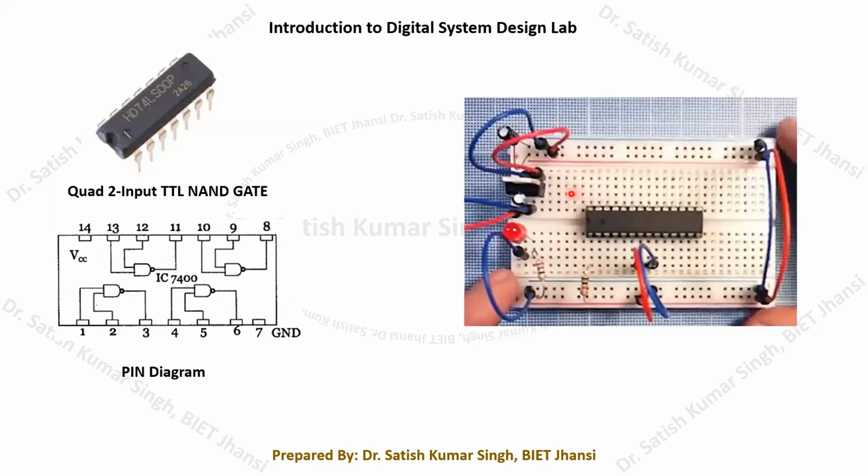Okay, similarly here again it is connected vertically. You remember that it is shorted vertically. So to connect an IC to this particular breadboard, we have to connect one side pin to this particular top section, and the other side pin should be connected to the bottom section.